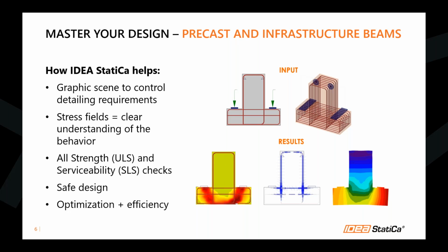I would compare the compressive stress with the design resistance of concrete. I would design reinforcement based on the tensile stresses, and I would think that my design is fine. However, we saw that the structure fails for crack width check. And this is something what you might risk if you don't use more advanced approaches.